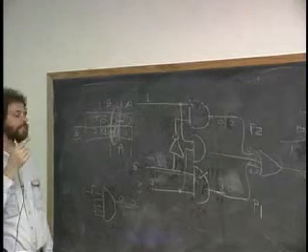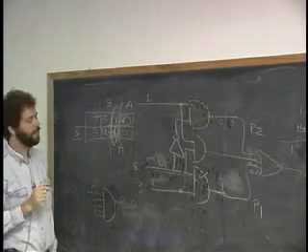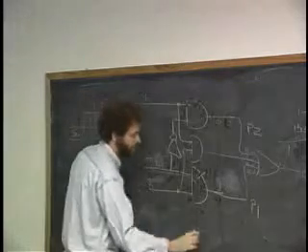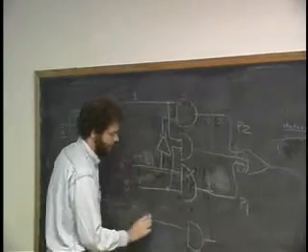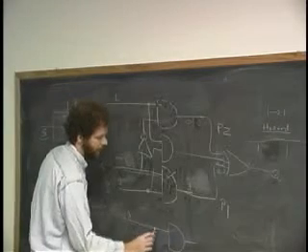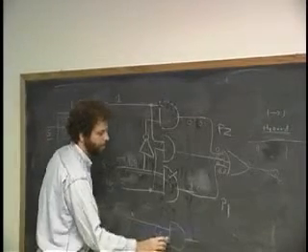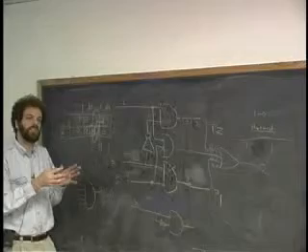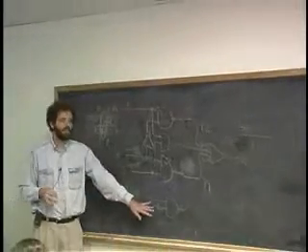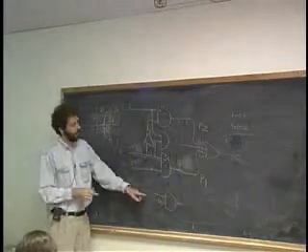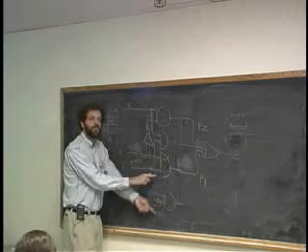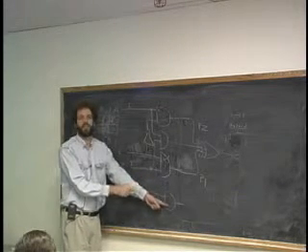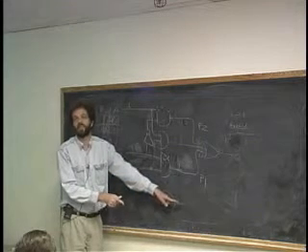It turns out that there is one degenerate case, which doesn't matter, which is if I have an AND gate and I have an input, let's call it X, and I feed it both X and X bar at the same time. According to the definition of sum of products, this is legal to do. And in this case, we have a single input change, which would result in a double input change to the AND gate, which could result in a glitch on the output.